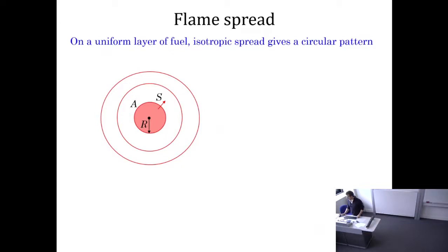Good. So now you can actually put all this together and come out with an approximation to a flame spread rate of a fire. So if you have a fuel, you are looking at the fuel from the top and it ignites in the center, okay? At some point, if the fire doesn't have a preferential direction, because it's not going upwards, or because all the fuel is uniform, then it will be circular, because the flame spread will be uniform in all directions. And after the fire has grown a little bit, the flame spread will be relatively constant.